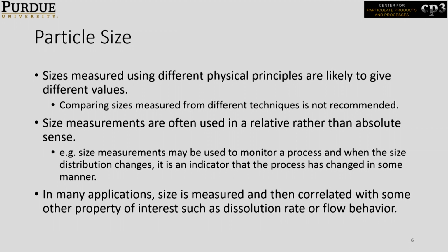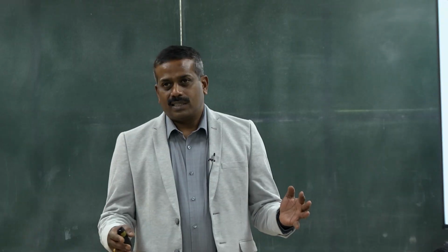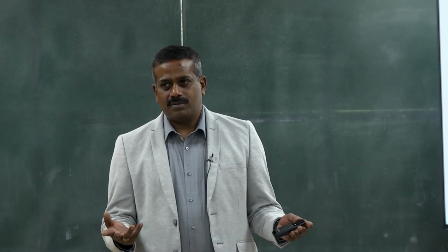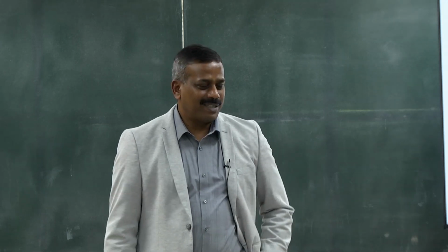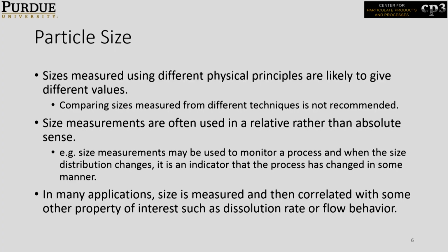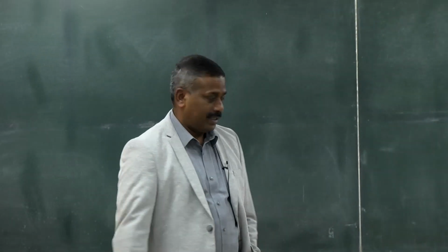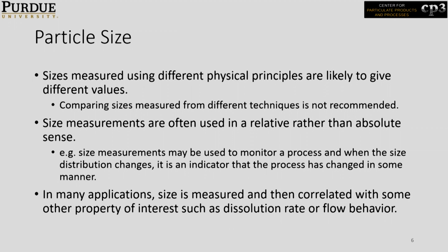For example, going back to the wheat flour milling example. What is the minimum particle size for wheat flour? You all have a better memory than me. 140 microns, right? So when you are measuring the particle size of wheat flour, we in general talk about whether the particles are around that 140 micron range. If it's above or below, we don't quantify that accurately. If it's closer, then we use that measure.